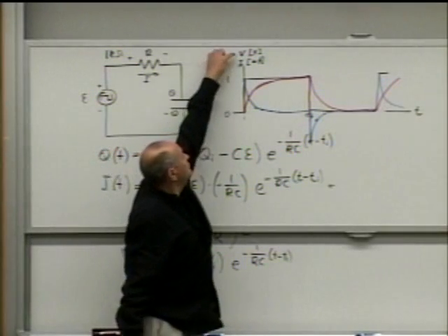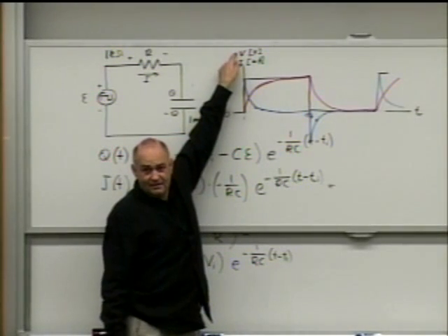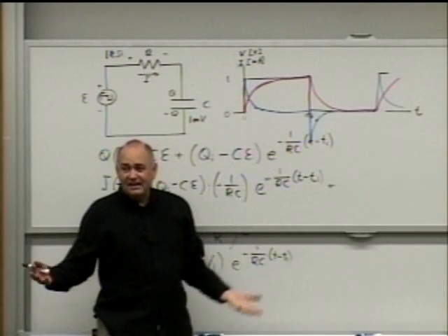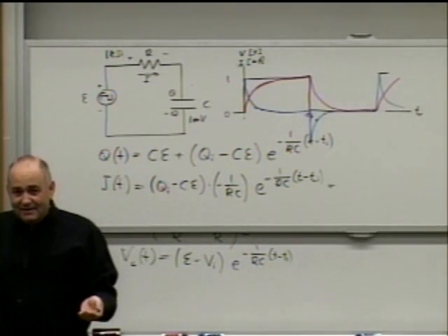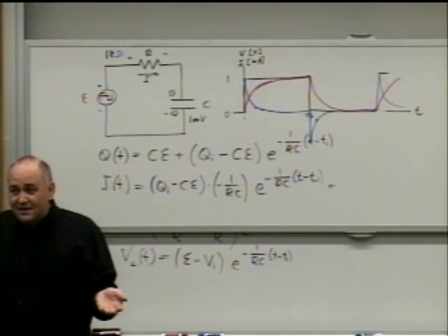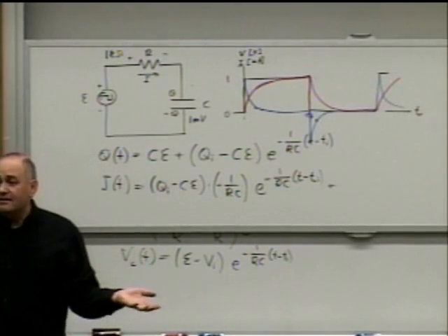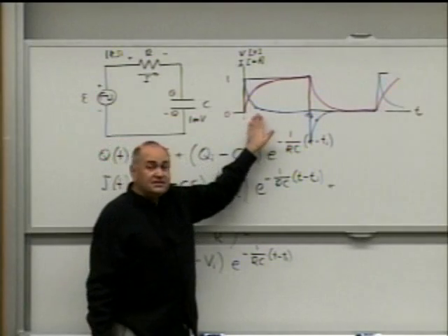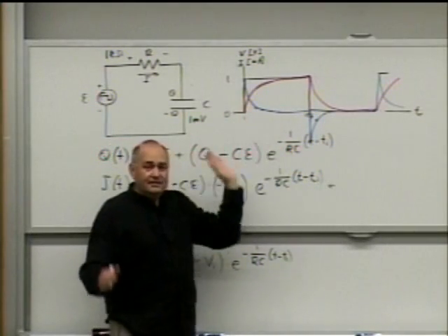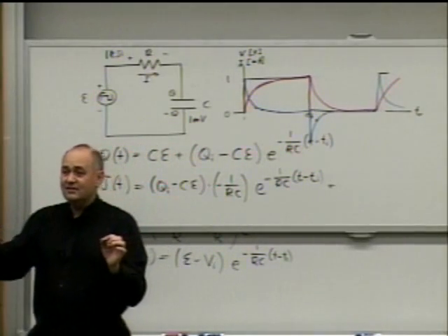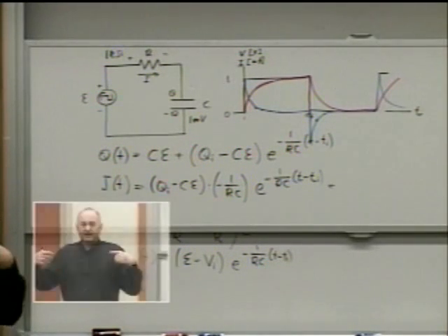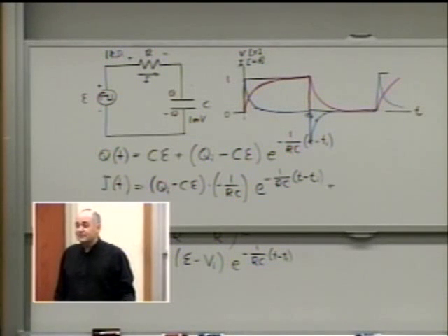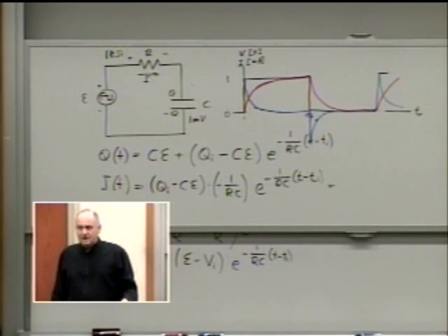However, you have to look at volts now, because I selected resistance to be 1 kilo ohm. So when we multiply by 1, we get 1,000 times higher value. Very good. I'm glad that you understand it. It's simultaneously a plot of current and voltage, because they are proportional in a resistor.